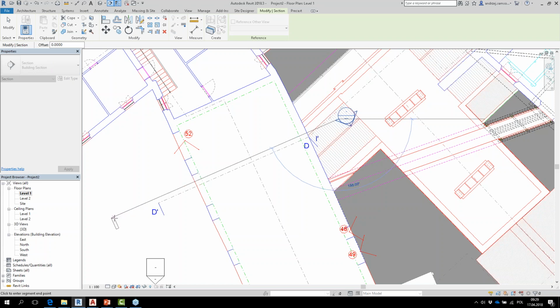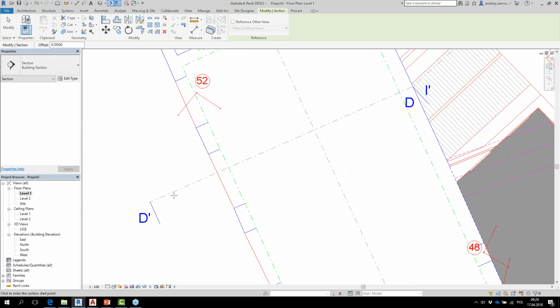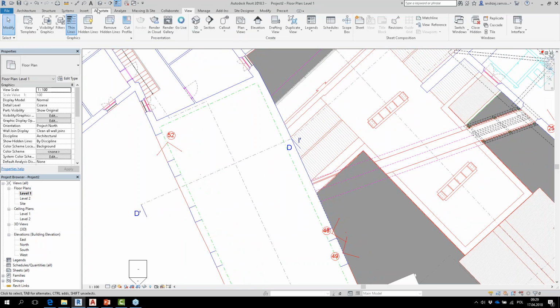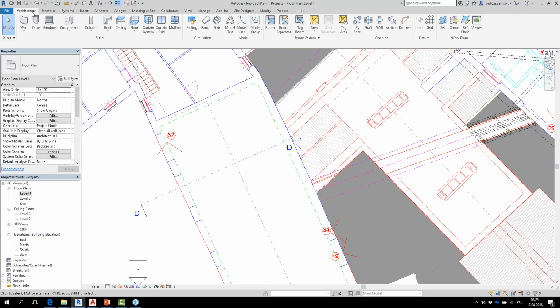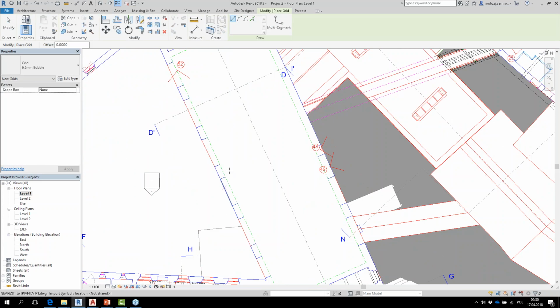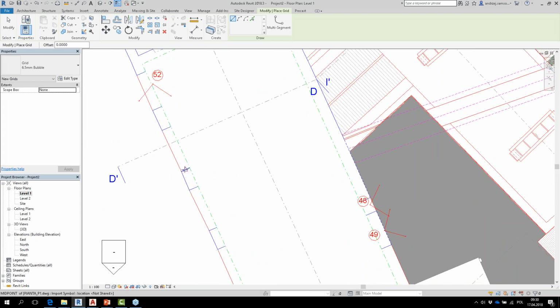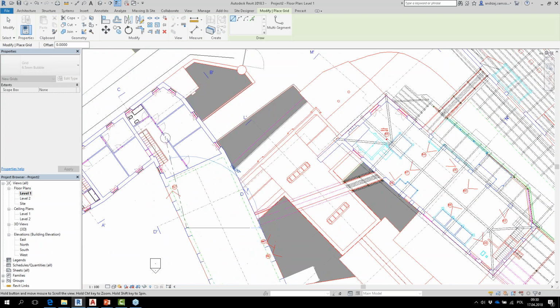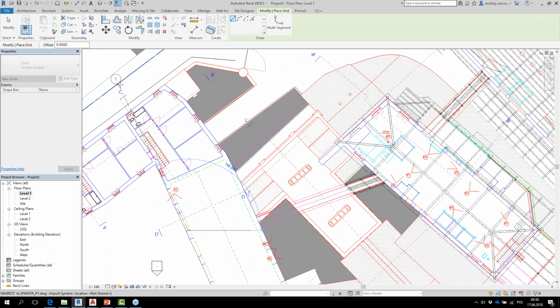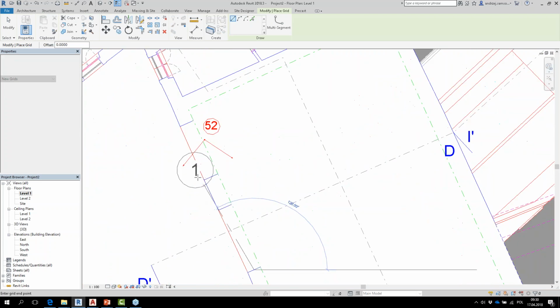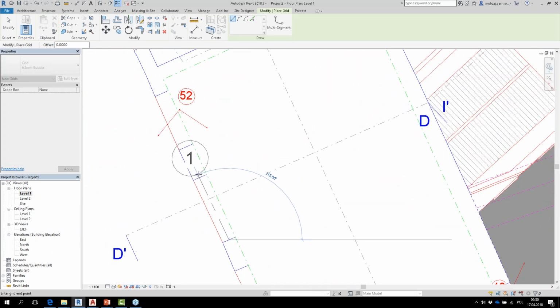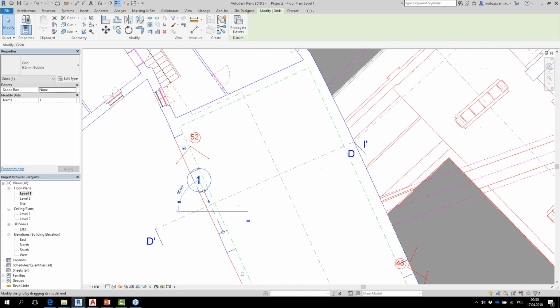What you can also do before the insertion, because sometimes it will not snap to the lines, is go to Architecture, and before I start drawing it, I can help myself by drawing grids. These grids will significantly help me to grab all these middle lines and so on, right?